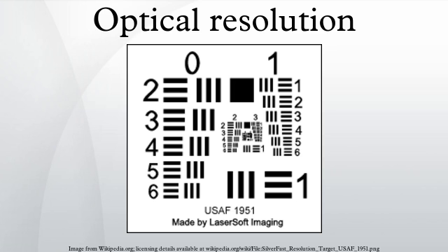Measuring optical resolution. A variety of measurement systems are available, and use may depend upon the system being tested. Typical test charts for contrast transfer function consist of repeated bar patterns. The limiting resolution is measured by determining the smallest group of bars, both vertically and horizontally, for which the correct number of bars can be seen.